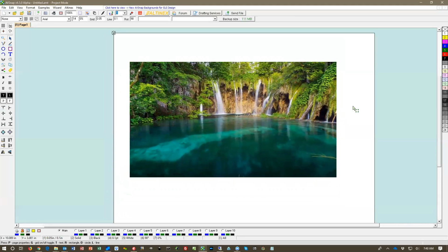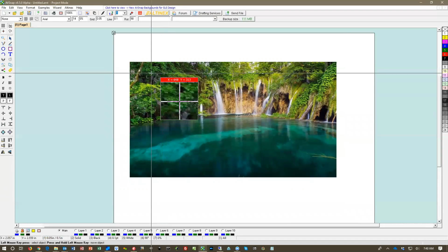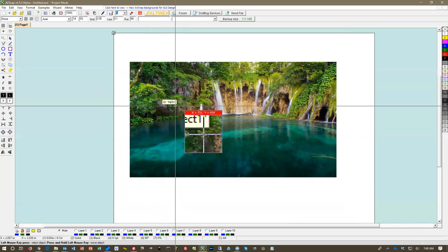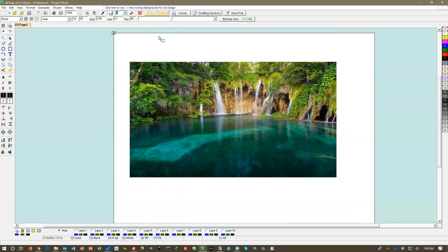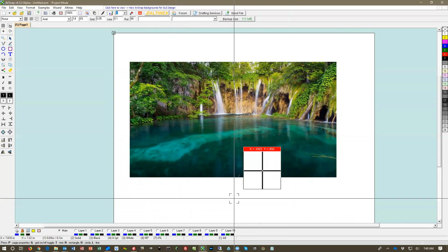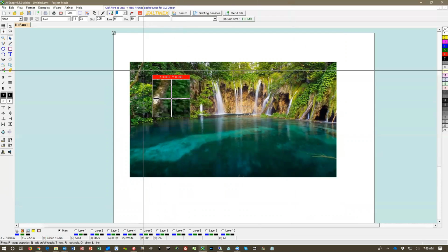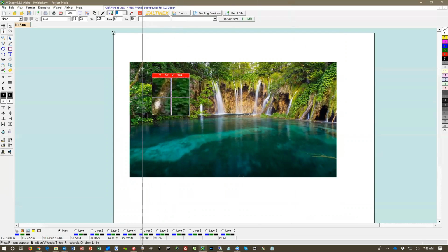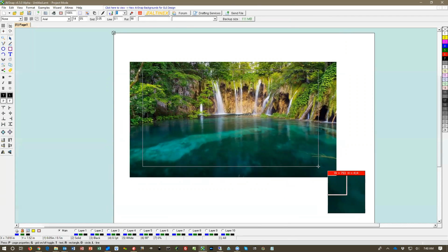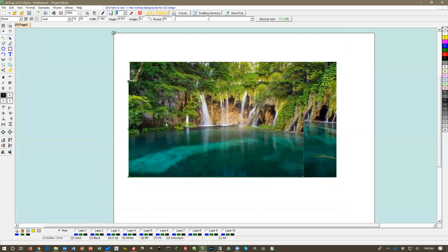All right, so let's do a little bit more with this image, and we're going to try to capture a little bit more precisely. If I press print screen, I get my cursors, and I also got the cursor here. So let's go ahead and escape it for a second. Print screen again. Once you're in this mode, you can also use arrow keys to move the cursor to a precise position. Once you get to the precise position, hit enter, and then go to the next point. And you can also adjust the next point exactly where you want to go until it's perfectly adjusted. And then when you hit enter, the image will be captured.